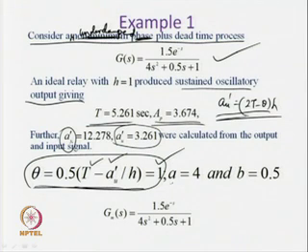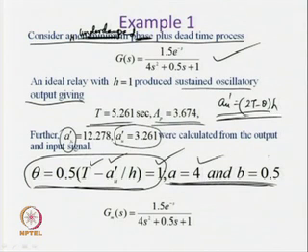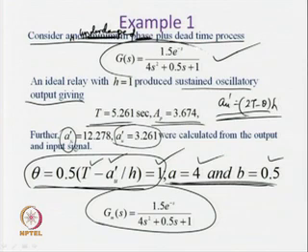Similarly, using 2 analytical expressions now, A and B can be obtained. Okay. So, A and B are estimated to be 4 and 0.5. Therefore, the transfer function model we obtained for the underdamped system dynamics is found to be quite accurate, and the model is very much equal to the original system dynamics. This is how we see the efficacy of the expressions we have derived for estimating the dynamics of an underdamped system.